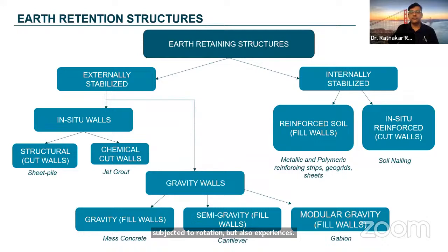The last one is the service life. We design temporary earth retaining structures when the service life is less than 5 years, or permanent structures when the design life is more than 5 years, usually 75 to 100 years.